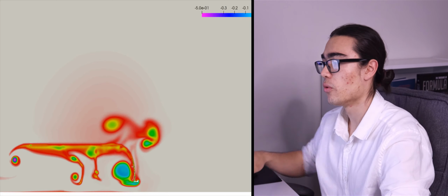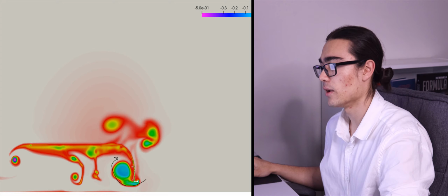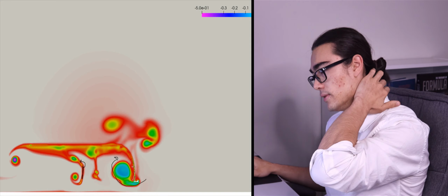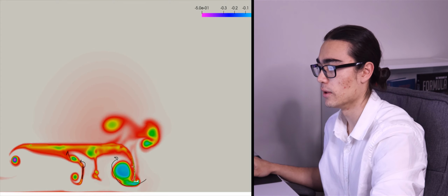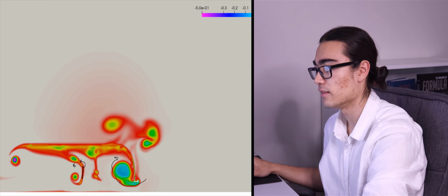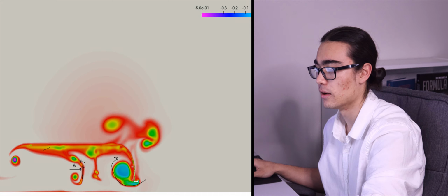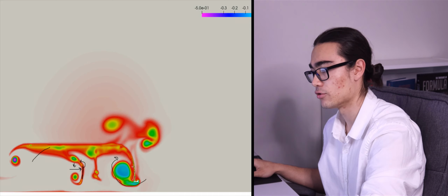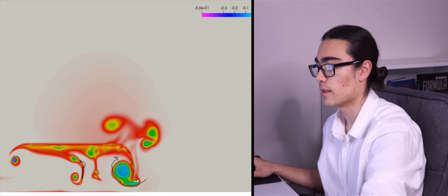So as you can see, we've developed quite a loss coming in from the footplate here. You can also see that our strake here has shed a top vortex because of our outwash. Now, this isn't ideal if we can't really control it. This is going to get sucked up by the front wing there. It would be really nice if we could keep this vortex traveling with this vortex and create that same effect to laterally expand the airflow outboard without the cost of balance if we were to just cut down our inboard section front wing to get lateral that way. So that would be really nice. I'm not sure if that's possible, to be honest. Not looked at that too much.